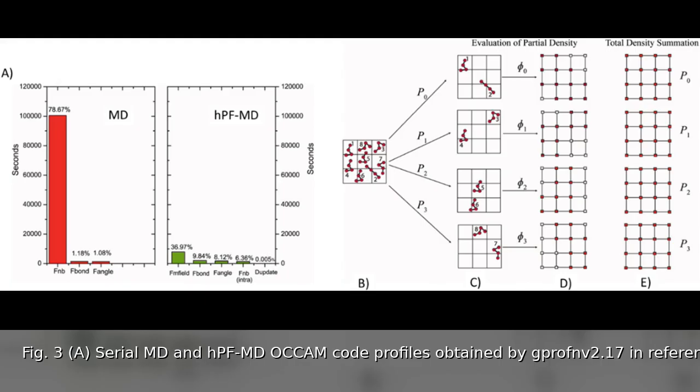Molecules are allocated to processors based on molecular decomposition, regardless of spatial location. Each processor owns the particles of the assigned molecules and calculates the associated intramolecular forces. Density fields needed for non-bonded force calculations are computed individually per processor from owned molecules. Then, a global MPI all-reduce operation sums these partial densities across processors to obtain the full density field. This strategy minimizes communication overhead, as density updates are required only at predefined intervals, and force computations between updates are fully parallel without inter-processor communication. An example with 4 processors handling 8 molecules demonstrates this.